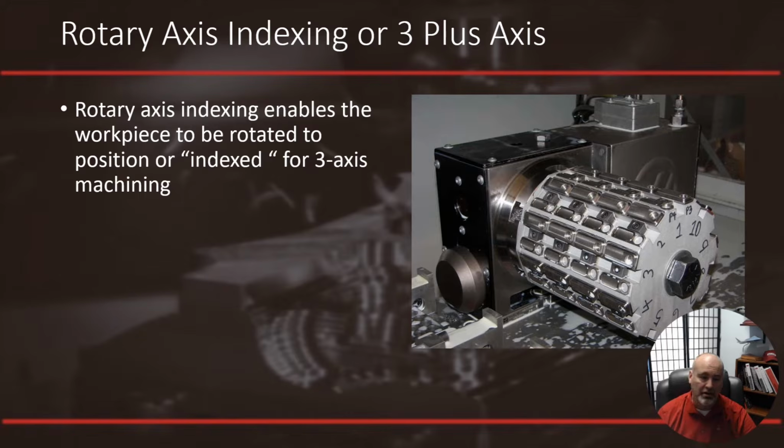It's cutting multiple parts per station and it looks like Mighty Bites holding down workpieces in 2 different stages of operation. So this allows us to do all these 3-axis moves at different angles on the faces of this multifaceted fixture.